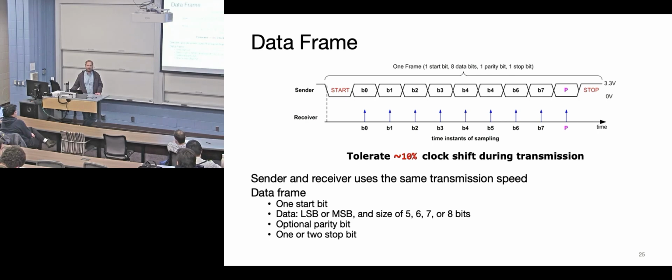One more thing, is the shift register internally clocked? Yeah, all the shift registers are clocked. And so on the device, yes. So that's why we have to sample. That's why you have to oversample this, because the receiving device may coarsely know what the clock speed over here is, but it doesn't know the phase of the clock cycle. When I say phase, it's like when you're pushing the kid on the swing, they have a certain rate they're going back and forth, and if you close your eyes, you have to match it, right? And you don't know what the timing of that swing is. And they don't know in this, so you oversample to guess, and then you can sample in the middle of each one of those bits where the blue arrows are.